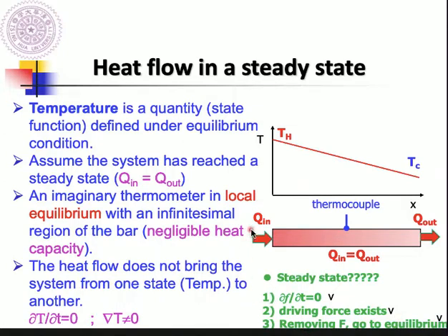And by the way, some people were concerned about whether, in reality, we can really measure this profile. Some people were concerned about the thermocouple we use to measure this temperature profile, because this is a heat flow, right? The heat is going to flow through this metal bar. However, there's a thermocouple which we use to measure the temperature profile. We also observe some tiny amount of heat flowing through the thermocouple, which interferes with the heat flow.